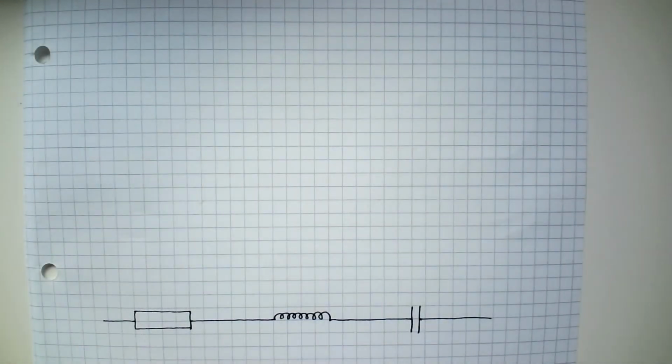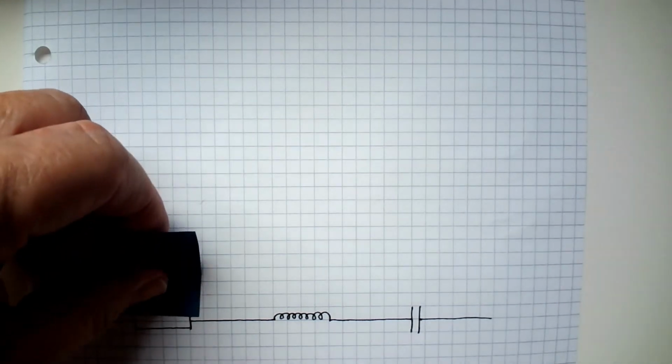So now we come to the matter of impedance. And to explain impedance, I thought I'd do it visually or pictorially rather than using just numbers to make it easier to understand. Here we have a part of a circuit which has a resistor, an inductor and a capacitor. Now the resistor may be a real resistor, or it may just be representing the total resistance of the wires in the circuit. But either way, there's a resistor here, and resistance isn't affected by frequency as the other components are.